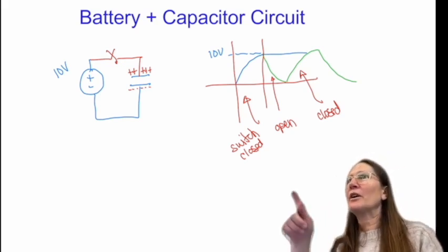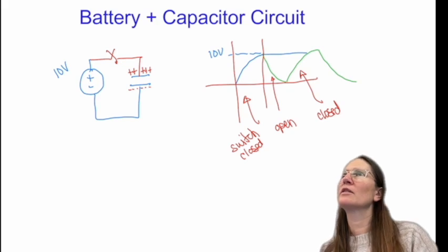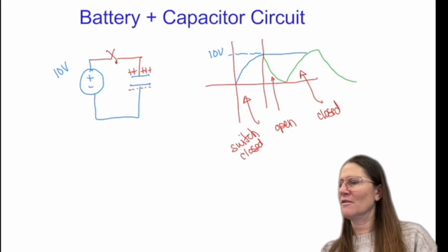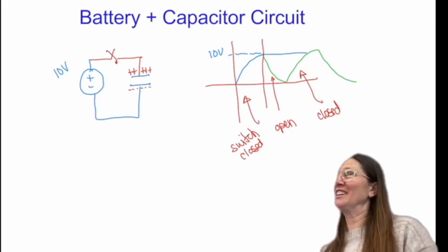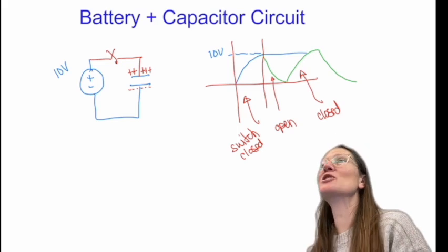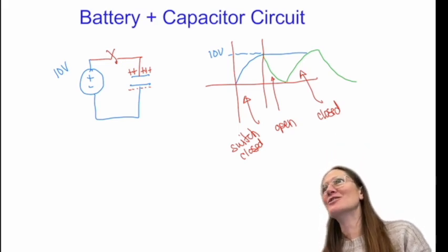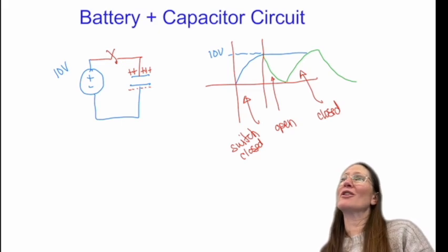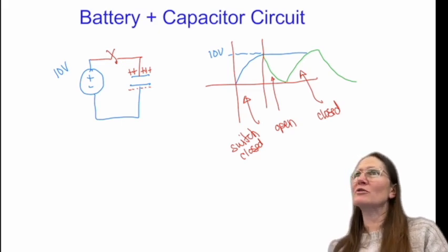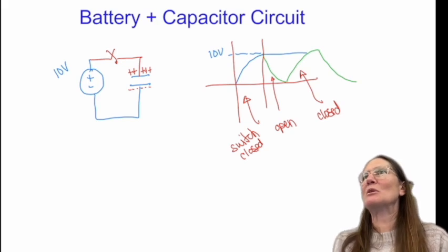Yes. How is the time constant calculated if there's not a resistor in that circuit? It's harder to do the time constant, so you can't use that technique to solve for it because we don't have a time constant. Physically, there will be what's called a parasitic effect where the wires themselves have some resistance, but it will be really small.